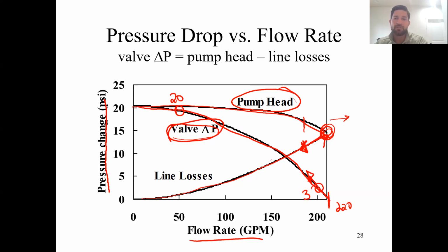The general rule of thumb that the author says in the textbook is if the ratio is greater than, I think they say 4 or 5, use equal percentage. So 20 divided by 3 is like 6.7. That would mean we would use equal percentage. And again, if you do the rigorous analysis, they become about the same if your delta P difference is about 2 to 3. Equal percentage valve is going to work better in some cases. Linear valve will work better in others.